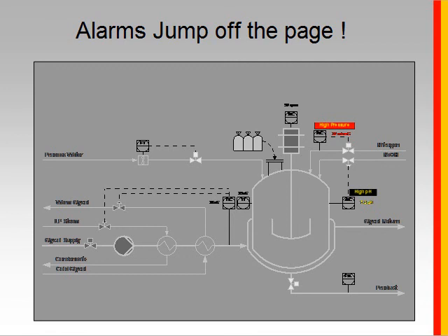But what it does say is, if you're going to use specific colors for alarm, in this case yellow and red, then you shouldn't use those colors for any other part of the HMI design. The previous screen we saw that some of the piping and the flow was colored in yellow. That would be a violation of what the standard recommends.